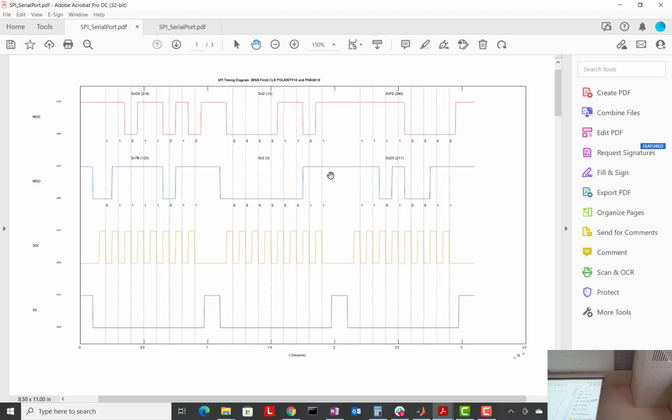So we'll have to keep on thinking about that as we get to a device. But notice, for the chip to send us anything, slave select needs to be low. Okay? When slave select is high, no data is coming into us, or out of us. Good. And then the clock.